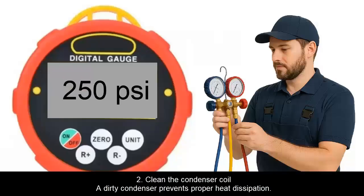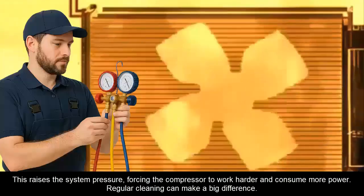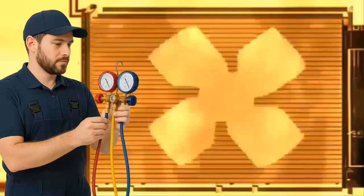2. Clean the condenser coil. A dirty condenser prevents proper heat dissipation. This raises the system pressure, forcing the compressor to work harder and consume more power. Regular cleaning can make a big difference.